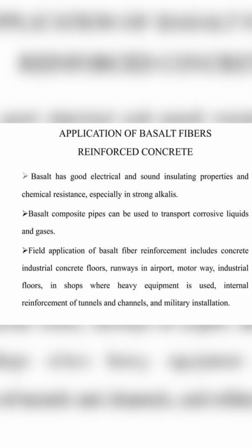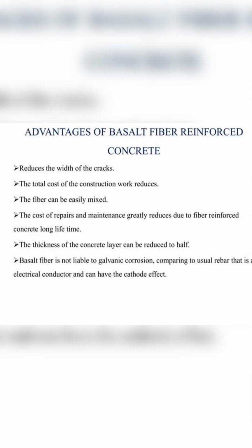The applications of basalt fiber reinforced concrete: it has good electrical and sound insulating properties and chemical resistance, especially in strong alkalis. The composite pipes can be used to transport corrosive liquids and gases. The field applications of basalt fiber reinforcement include industrial concrete floors, runways in airports, motorways, industrial floors in shops where heavy equipment is used, and internal reinforcement of tunnels and channels and military installations.